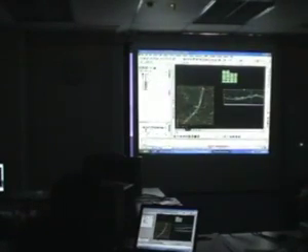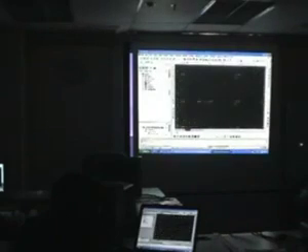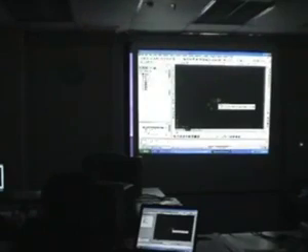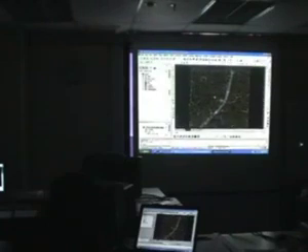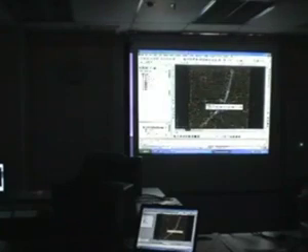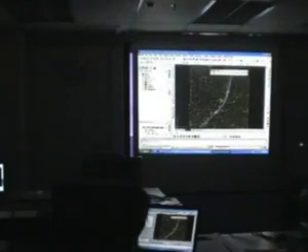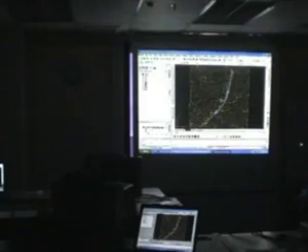I'm just going to zoom in so you can see these are actually all the points. The points are about the same as in Land Desktop, and I've already created the surface. Civil 3D is unlike Autodesk Land Desktop. In Land Desktop, to create contours, elevation banding and triangles, you have to go to Terrain and create them yourself. In Civil 3D, there's no Terrain option here. Everything is managed on the left-hand side.